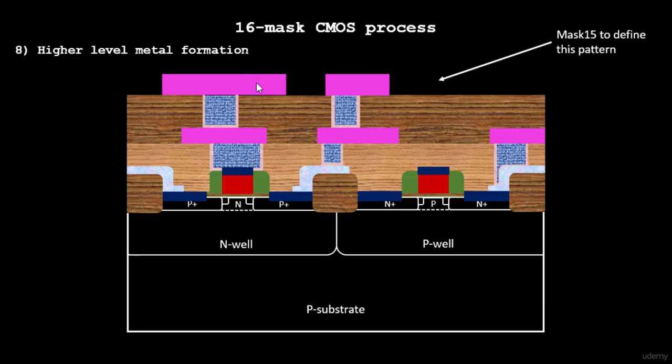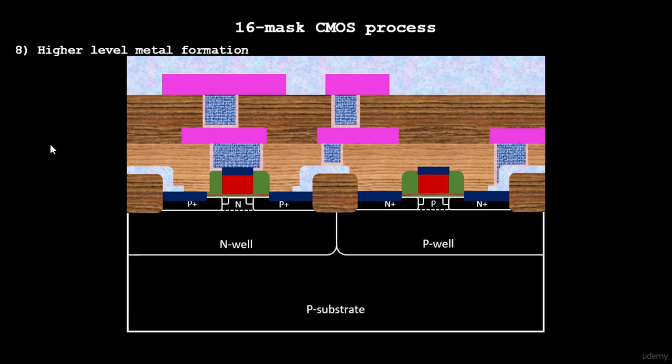That is done through RCA cleaning. RCA is nothing but a solution. It consists of various combinations of various parts of chemicals. For example, in this case, the RCA cleaning will consist of 5 parts of deionized water. Deionized water is a cleaner form of water. Then we have ammonium hydroxide. We'll use 1 part of ammonium hydroxide, and 1 part of hydrogen peroxide. By this combination, we can create a solution that is used for etching of titanium nitride, and that process is referred to as RCA cleaning.